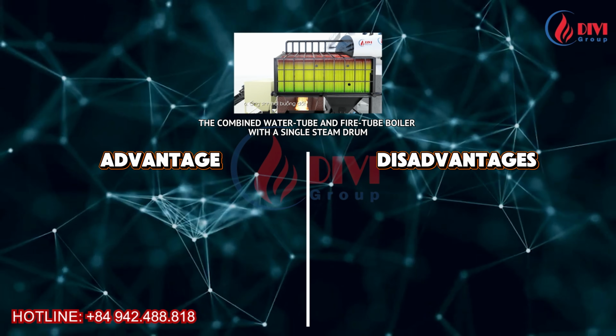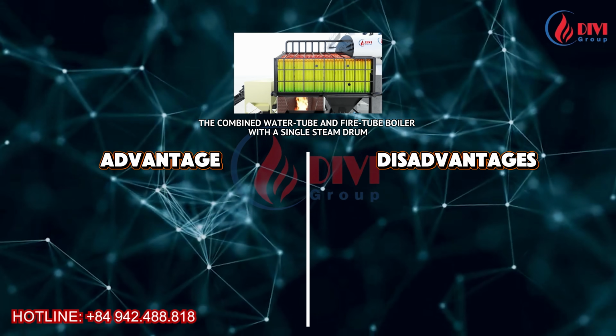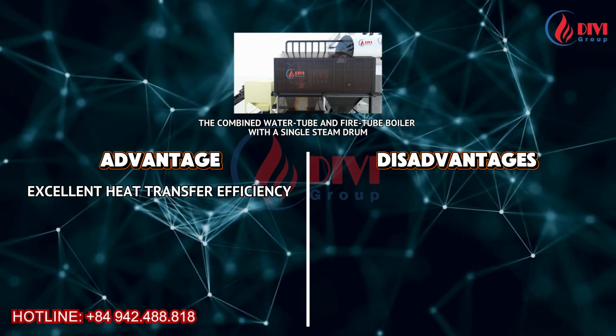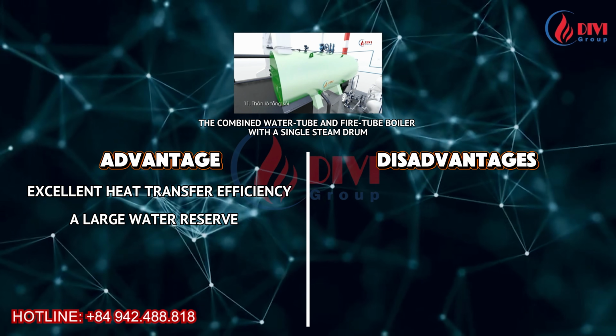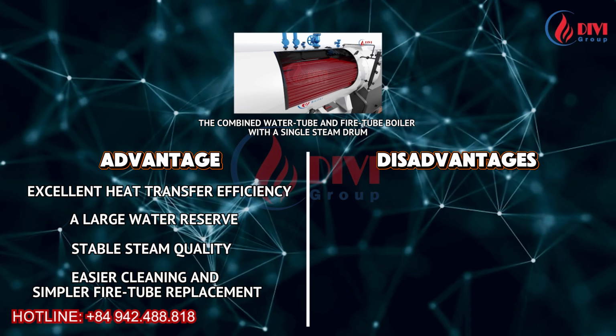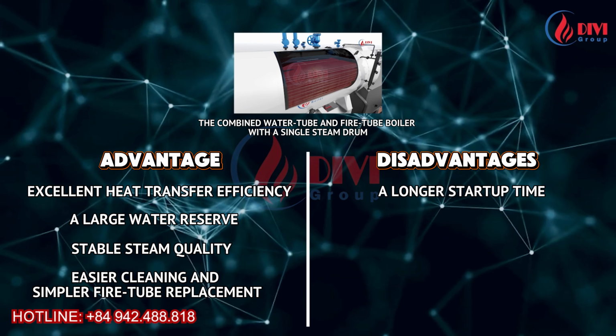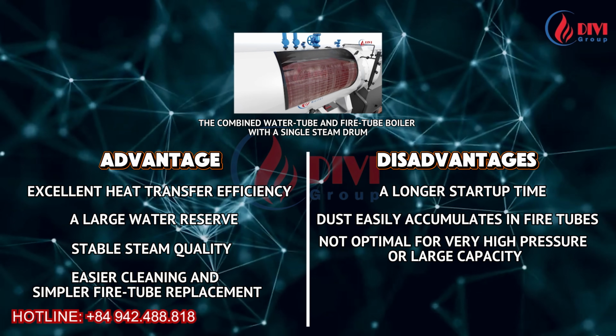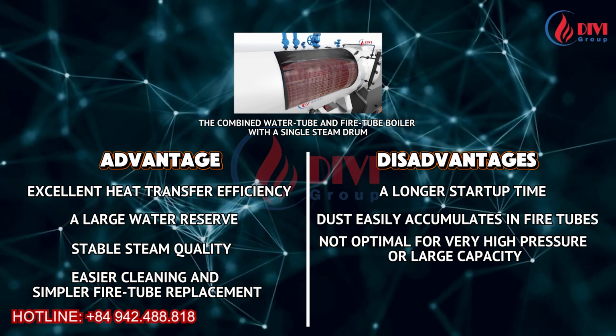To summarize what we've discussed so far, here's a quick recap. The combined water tube and fire tube boiler offers excellent heat transfer efficiency, a large water reserve, more stable steam quality, easier cleaning, and simpler fire tube replacement. Its limitations include a longer startup time, more frequent ash buildup inside the fire tubes, and lower suitability for very high pressures or very large capacities.